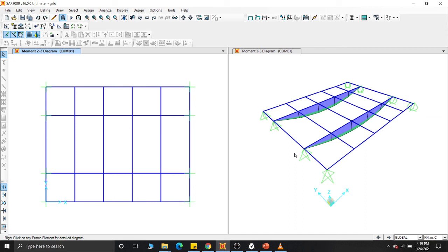So this grillage analysis is something that we use in the preliminary stages of design for you to have an idea about what the sizes of sections that you're going to need. So this is the simple way of doing an analysis for a box girder bridge.